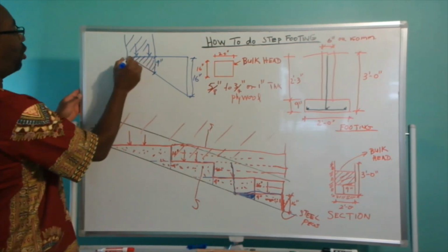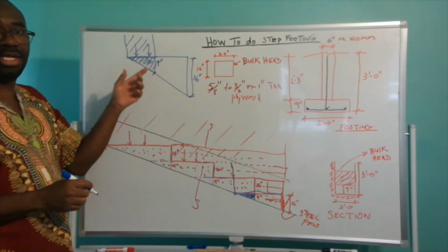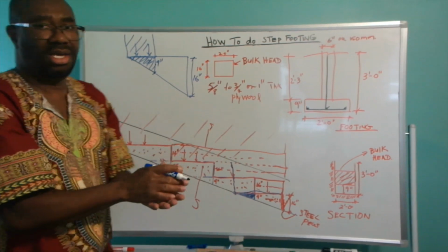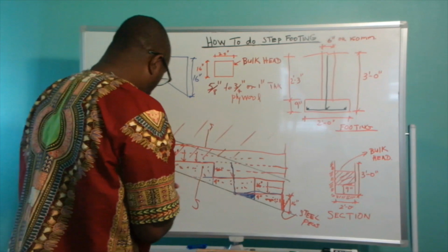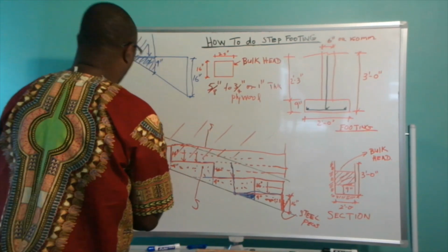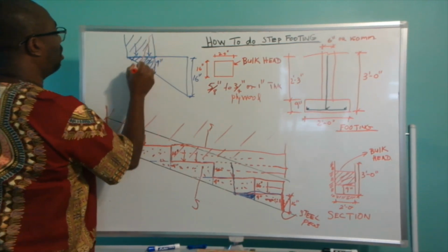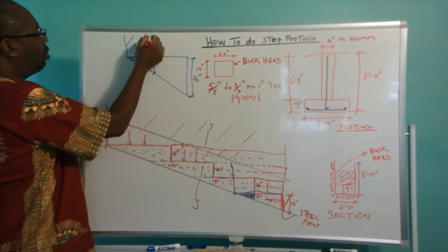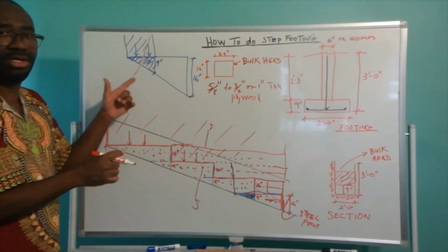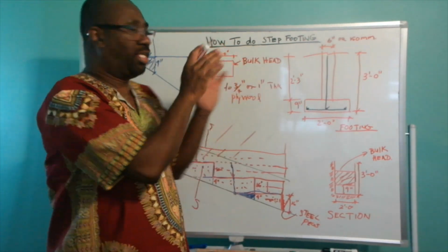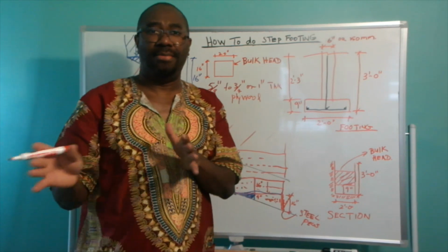this portion here is not going to be able to deal with the weight of the building, because the concrete there is not thick enough to carry the weight of the structure. And you're going to end up with a cracked foundation. That is going to crack the wall also, due to the crack in the foundation. And this situation is very tedious to deal with, and it is virtually unfixable, if not impossible.